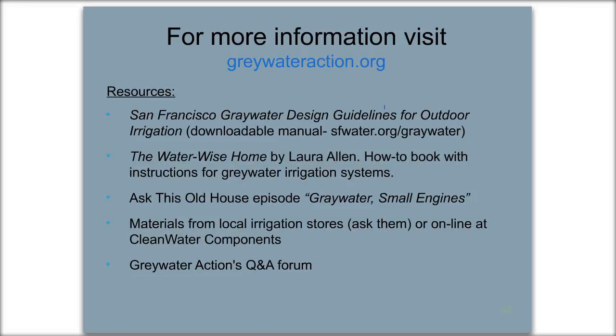How do you ensure that water equally goes to each plant? So that's a great question, and it has to do with the design of your system, and the systems are a little bit different in the way you design them. This is an introductory class, so we'll have more detailed classes on each particular system throughout the series. But to briefly answer it, you design it first by figuring out how much water and how many plants. With the branch drain system, you design it in how you lay out the fittings. They divide the flow. In the laundry to landscape or pump systems, you can do things to control the flow, where you kind of even it out by adjusting your system after you build it. And if you want more water to one plant, you can have more outlets, or if you want less water, you can be a little farther away or have fewer outlets in that area. So there's a couple of strategies to manage the flow of water.